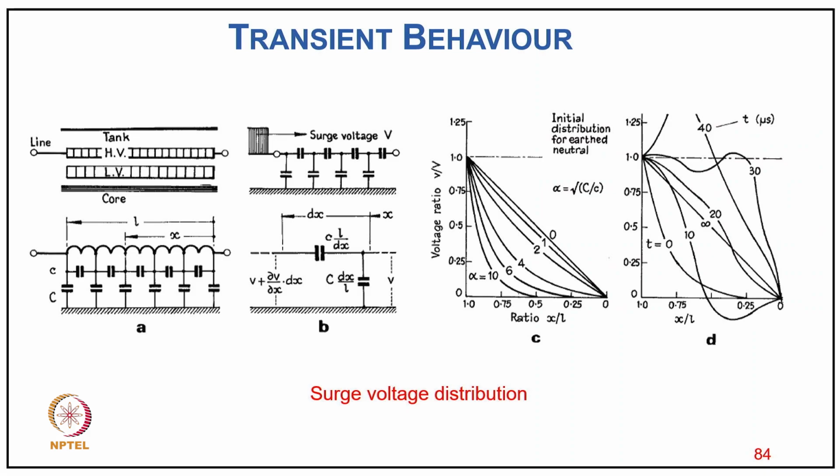And you can see how, typically because of the coupling capacitances and the surge voltage, this voltage becomes quite excessive across the distribution of the winding turns, which may really cause the surge voltage distribution across the winding and may affect your winding. Sometimes very excessive voltage may affect the insulation, typically causing a crack in the insulation, which, as time goes on with moisture and dust, really affects the insulation life.